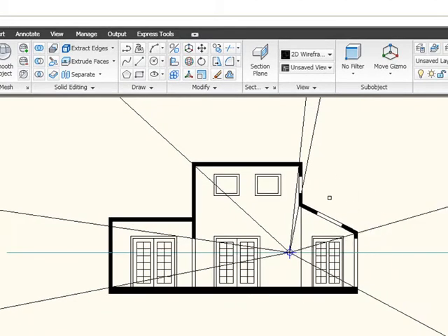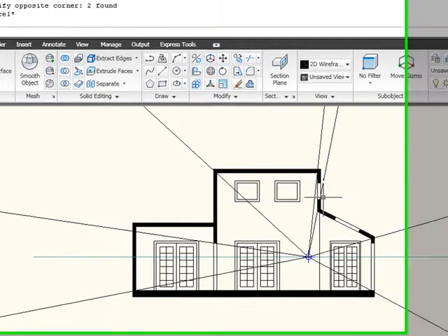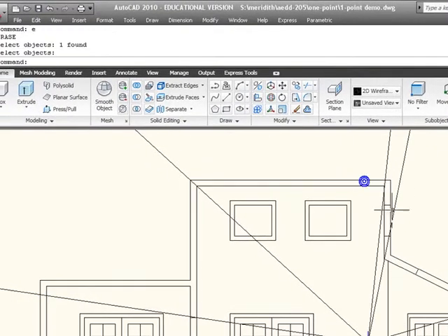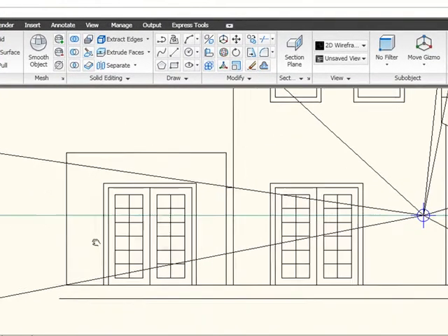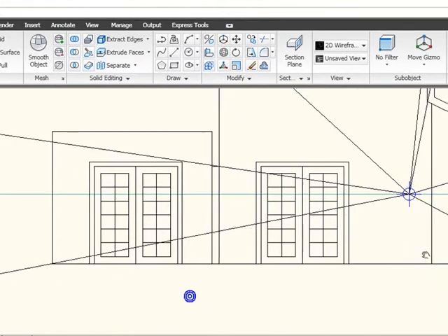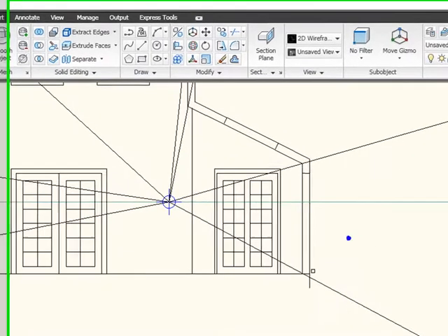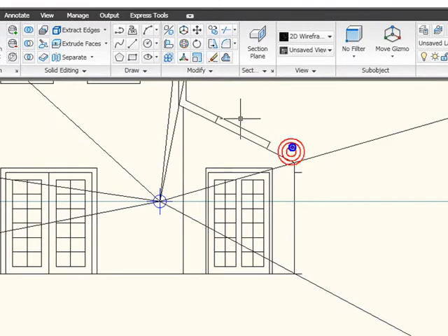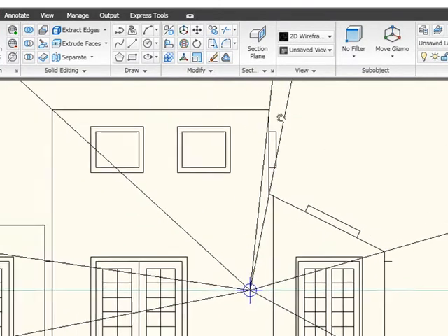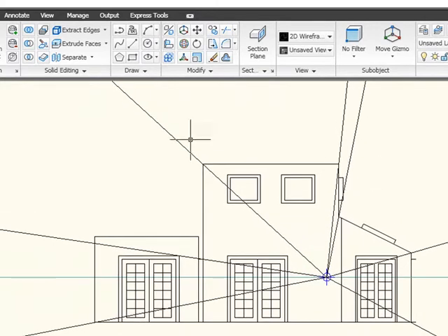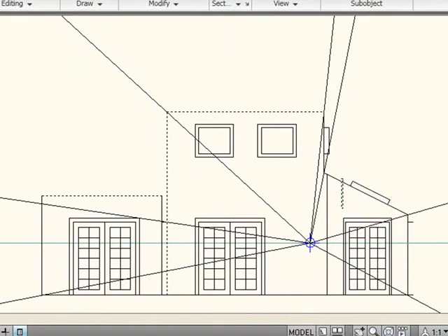Right, now just to make this a little bit more clear, I'm going to get rid of the hatch pattern, and I'm going to get rid of this outside line because we're not going to really see that. So there's the space that we're defining. I'm just going to keep a reference there for those windows though, because we're going to want to know where those are in a minute. Alright, so these become our walls. And if we trim to these boundary edges like we did before,